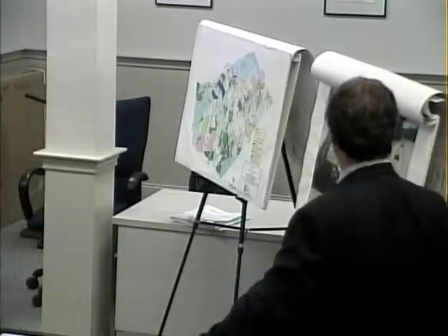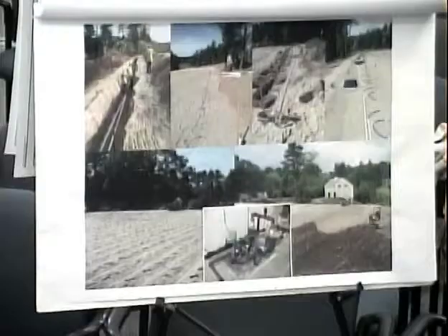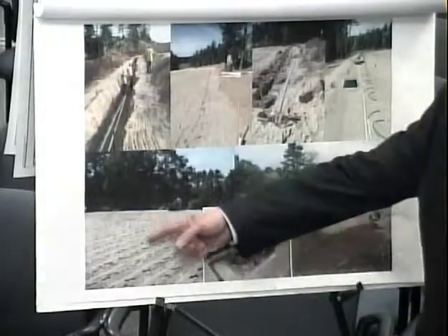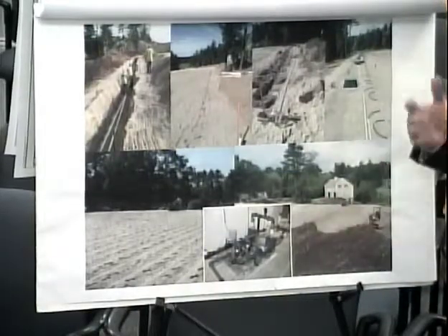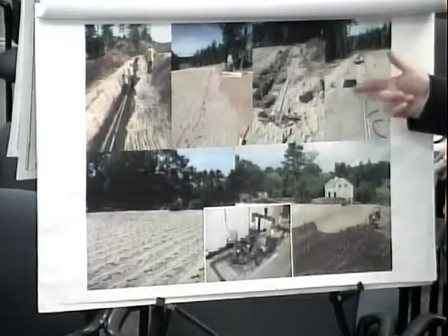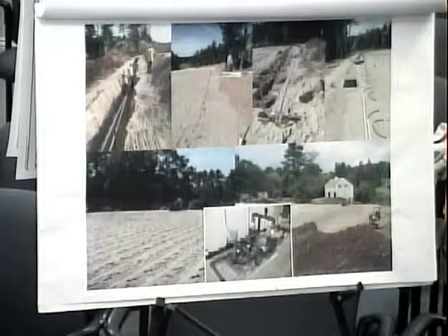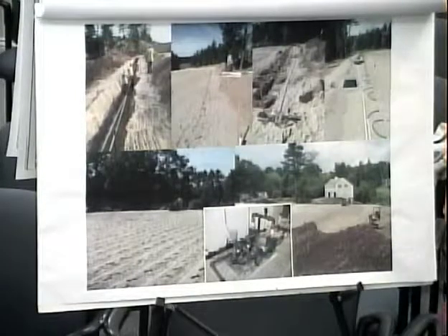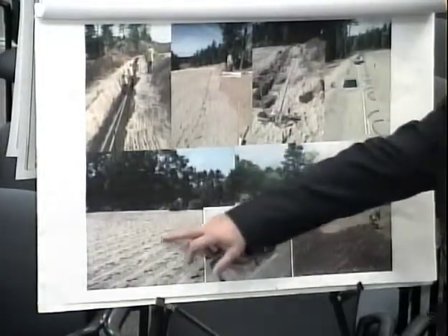And this is basically some examples of the drip system going in. You can see how it's just furrowed in. They usually use a ditch witch to put it in the ground. And then these are the loops and the emitters on the ends, and it's all buried. It can be used for recreational fields and other things as well. This is an open field. This one was brought up, you can see with a lot of Title V sand in here.